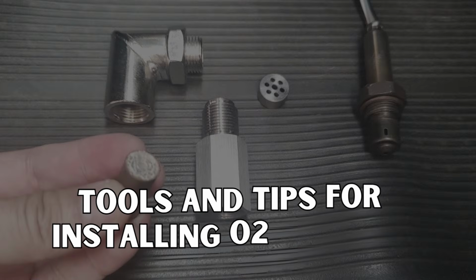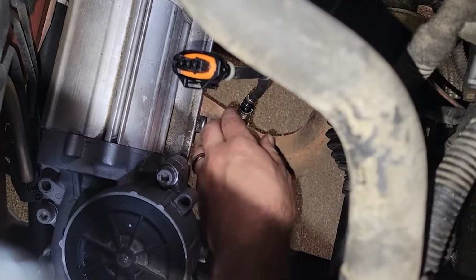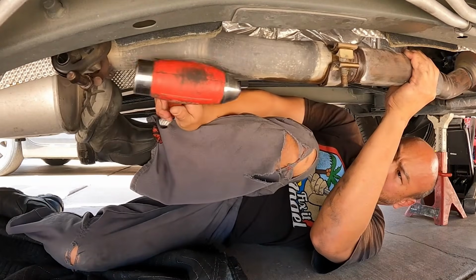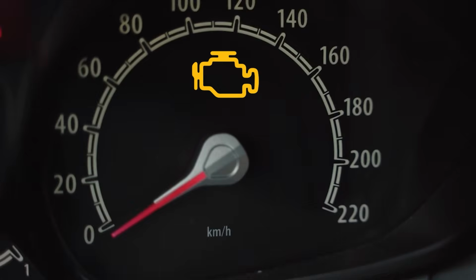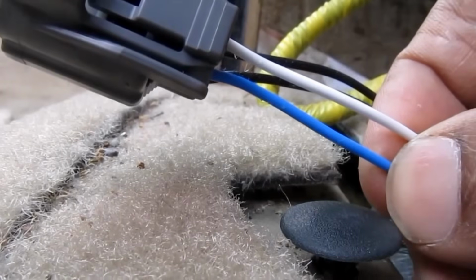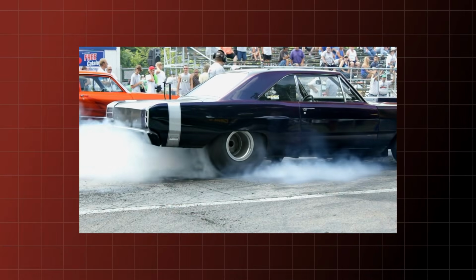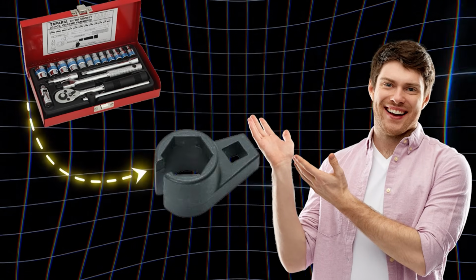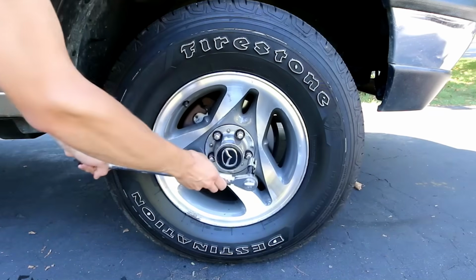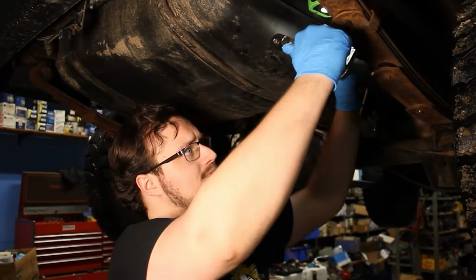Tools and tips for installing O2 spacers. Installing O2 spacers can be a practical solution for addressing catalytic converter issues, especially when trying to avoid triggering check engine lights due to emission sensor readings. However, the process requires careful attention to detail, the right tools, and a basic understanding of how your exhaust and emission systems work. To begin, gather essential tools: a socket wrench set, an O2 sensor removal tool, and possibly a torque wrench to ensure proper tightening. It's also helpful to have gloves and eye protection for safety.